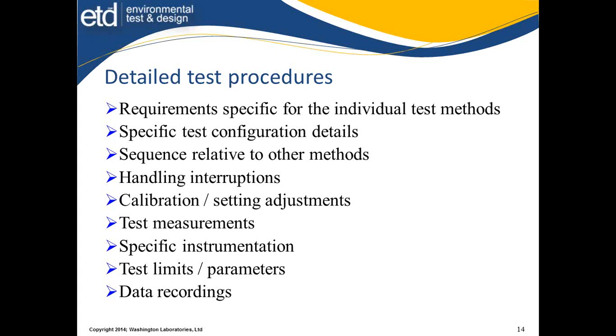How am I going to record the data? What's my output going to be from this to support inclusion into the report? Don't forget that these things are important. You need to have the data collected. Any specific instrumentation that's required to monitor it, support equipment-wise, or to actually perform the test. You may need to have a multi-port thermocouple meter to get various temperatures throughout the product. But you also need to say that the measurement at X is the one I'm going to control from.